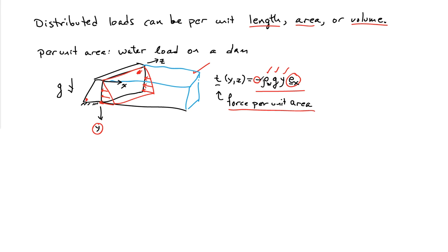So if we were trying to analyze the dam, maybe we'd be interested in replacing this distributed load over the face of the dam by some kind of simpler force system, maybe a point force acting in the middle of the face of the dam is what we would actually do.